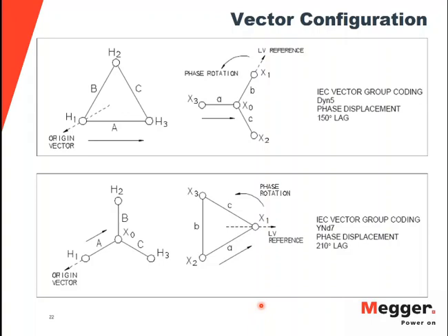So you're doing this make before break connection, and then we give you a good indicator, like if you saw our test results, we give you a pass or fail if we do that make before break connection. But if you do have an occurrence where that break happens first and you have an open circuit, we will discharge all that energy through the test set, through ground. Both the test set and the test technician will be protected there as well.